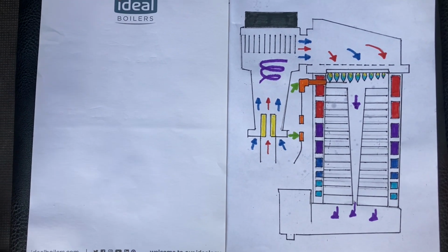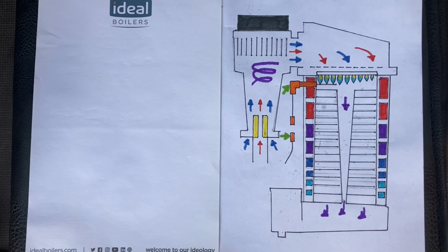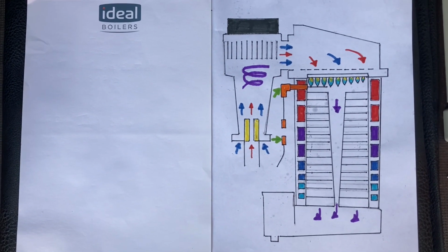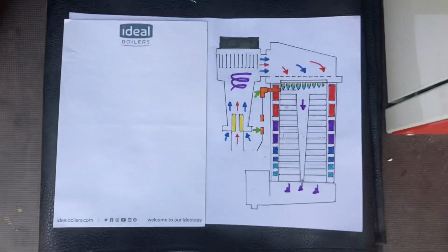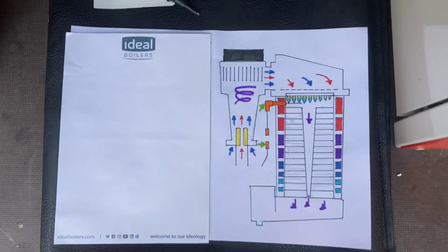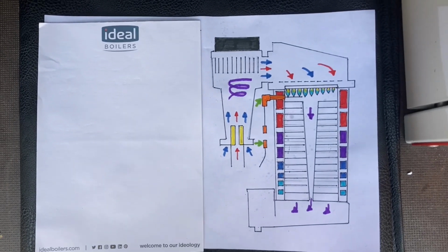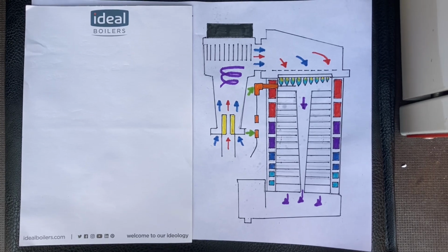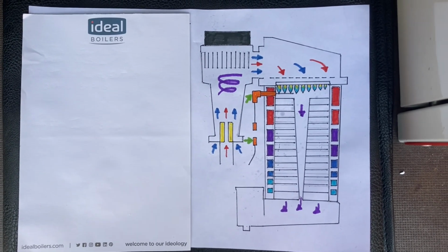I thought I was looking in the right direction, and I think everybody would do the same, but it dawned on me after a while. Even after I took the burner out and looked at it to see if the heat exchanger was blocked, I couldn't see anything. But what I did notice was there was cat hair all inside the boiler. It was full of it, and the rubber bung that you use to test the fluid integrity was missing.